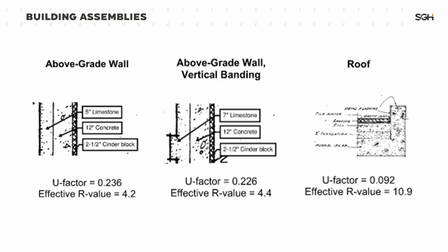It's important to note that a lot of heat loss is happening at the walls, and also the majority of this building envelope area is opaque walls. There are very few windows and they're very small. They're actually only about 4% of the overall envelope area. So we knew going into this that any changes to the window assemblies would not have a drastic overall effect on energy performance.